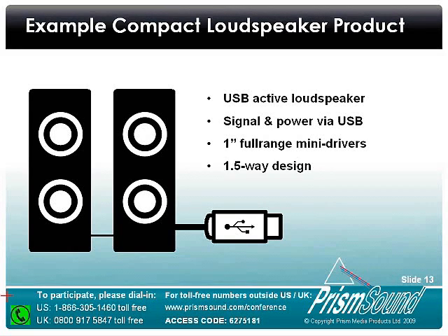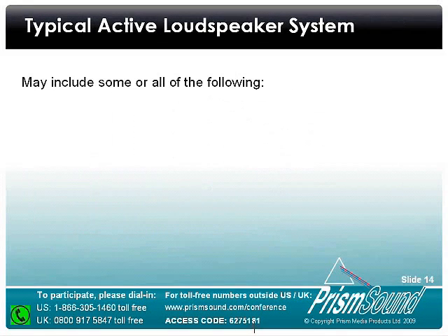It's a stereo system, and it's a 1.5 way design in that there is one channel of power amplification and there is a capacitor in parallel with one of the drive units, so that at high frequencies only a single drive unit radiates, and at low frequencies both drive units will be radiating. And it's a sealed enclosure. So that is my demo system for today. That's what I'm going to be using as my equipment for analysis.